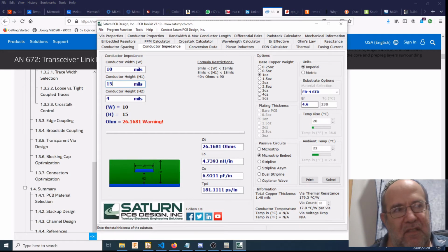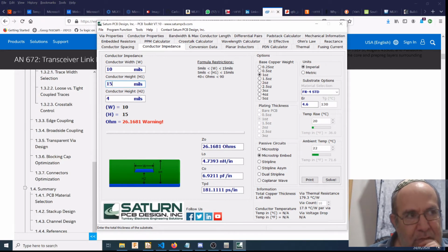This is a very important point. Every PCB person can tell you that when routing DDR data lines, one needs to keep the length the same.